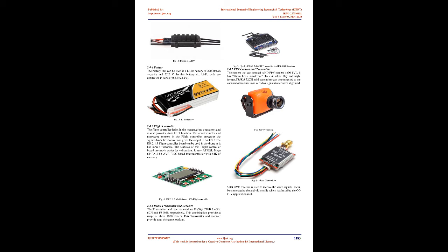2.4.1 Motor. Outer runner BLDC motors, in which there are no brushes, have a permanent magnet. The RPM of the motor can be controlled by varying the input current. This T-motor MN 7005 KV115 motor and P24x7.2F propeller produce a maximum thrust of 4,783 grams.